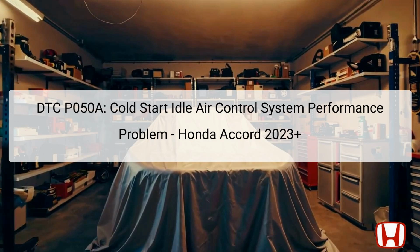The PCM continuously monitors the performance of key components involved in engine air intake and adjusts airflow to maintain optimal engine performance. Key components impacted may include the throttle body, mass airflow (MAF) sensor, and intake air temperature (IAT) sensor. Proper diagnosis is critical, as ignoring this DTC could lead to deteriorating performance, increased emissions, and poor fuel economy. This guide will outline detailed steps to troubleshoot and resolve the P050A code effectively.